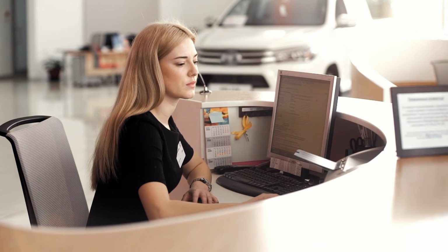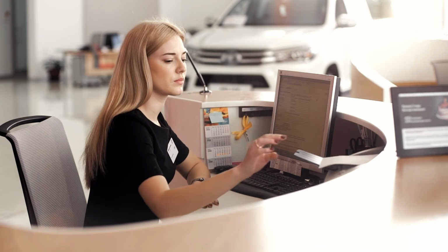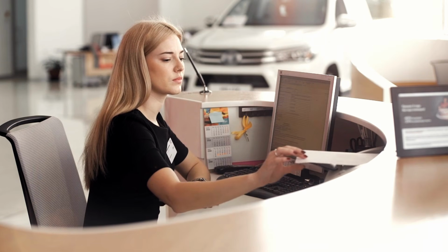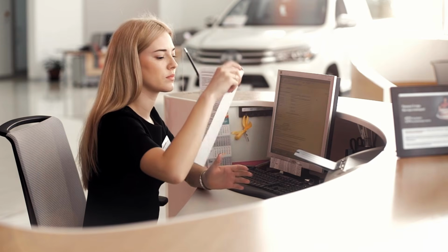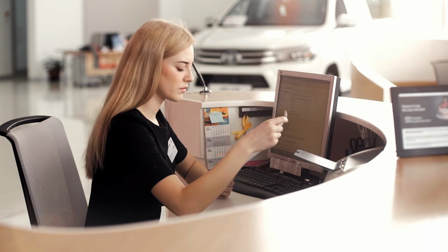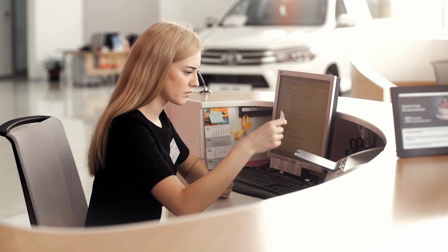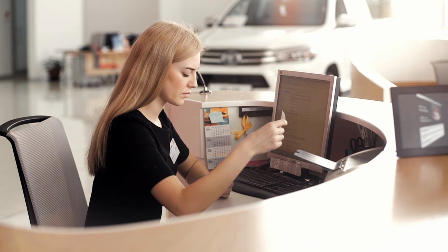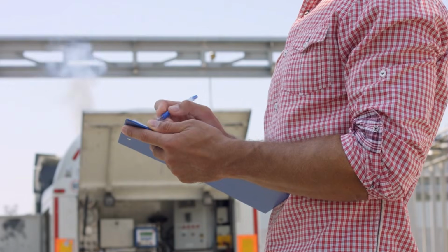Aftermarket oiled performance filters, cone filters, drop-in oiled elements are a specific risk factor. Excess oil from an over-oiled filter element coats the MAF wire in a layer that is chemically resistant to cleaning and will require sensor replacement rather than restoration. If you use an oiled performance filter, inspect the MAF element every 10,000 miles. If you run an OEM paper element replaced on schedule, a MAF inspection and cleaning every 30,000 miles is sufficient preventative maintenance. Here is the homework.